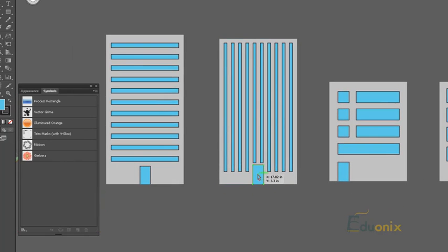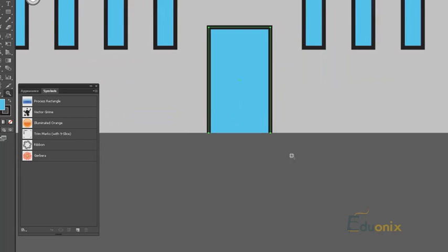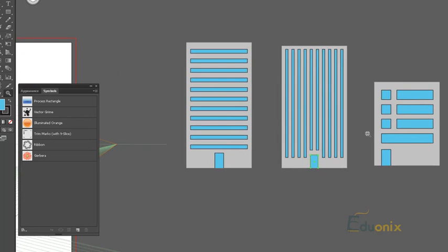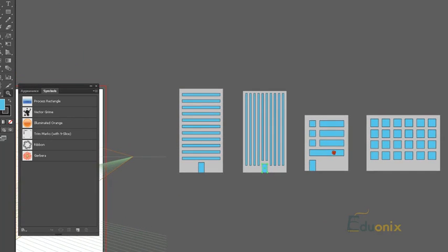In fact, you don't even really need doors. Some of these can also be a little bit small. In the end, you should have a couple shapes like this. And we're only going to be doing 4 buildings, but we may repeat 1 or 2. So let's go ahead and group these all individually. Just select them, highlight over them with your tool, and then Control-Shift-G on all of them, because we're going to be regrouping them from scratch.